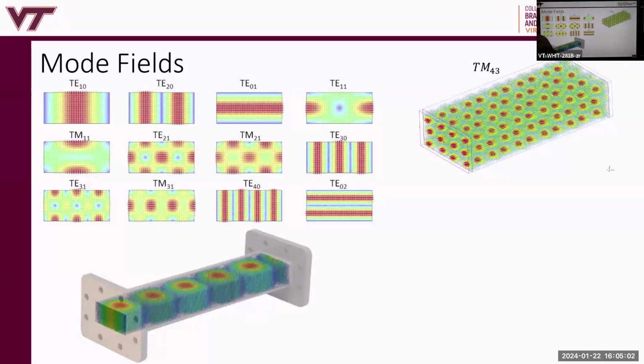It'll repeat along the z direction, and you get something like this. If you take this modal distribution here for the TE10, and this is both time and space changing, right? But if you fix time, if I pause this animation, then I look at different cross-sections, they are just this cross-section multiplied by e to the minus j beta z, all of them, right?